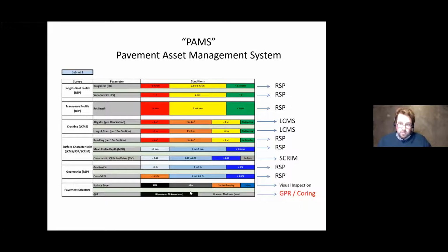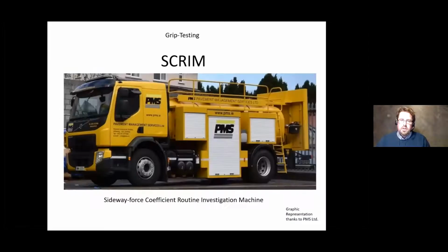It's quite a substantial amount of work to carry out, but it gives you good guidance in terms of a national network, what you're doing. I wouldn't base a design off the GPR that you're getting from the PAMS data. If you're using GPR, you'd want to get more site-specific GPR data carried out.